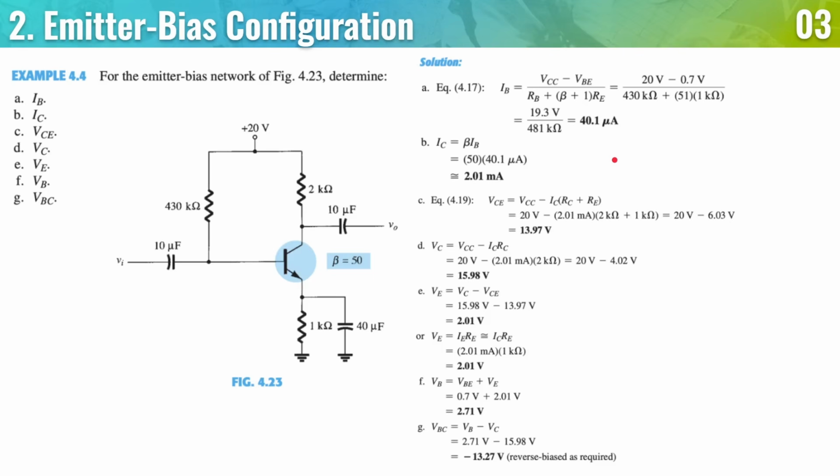So next, VC is equal to VCC minus ICRC. So basically, it is just saying what is the voltage here minus the voltage here. So that is why it is VCC minus ICRC. Again, ICRC can be rewritten as VRC. Again, VC and VRC are two different things.